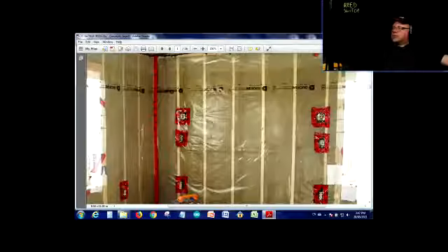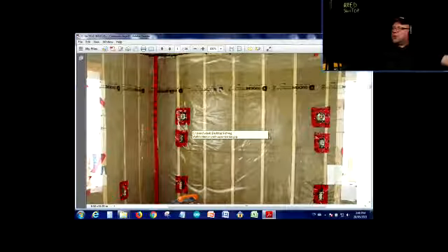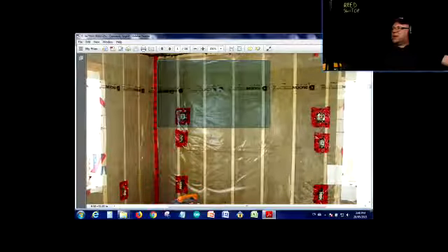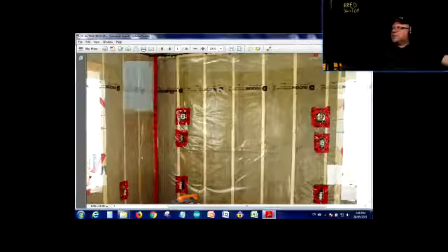What is this red tape? It's not because the government came here and put some rules and regulations and they call it red tape. No, it's the other red tape. It's called tuck tape, like tucking in. Let me tuck you in, okay? Tuck tape. So that's when you put that, you basically are sealing that. So if there's one piece of the vapor barrier here, and then there's another piece here, they join here. So then just to make sure that this thing is unpenetrable as much as possible, you're going to close the gaps with the tuck tape, and all that goes to all the openings that are there.